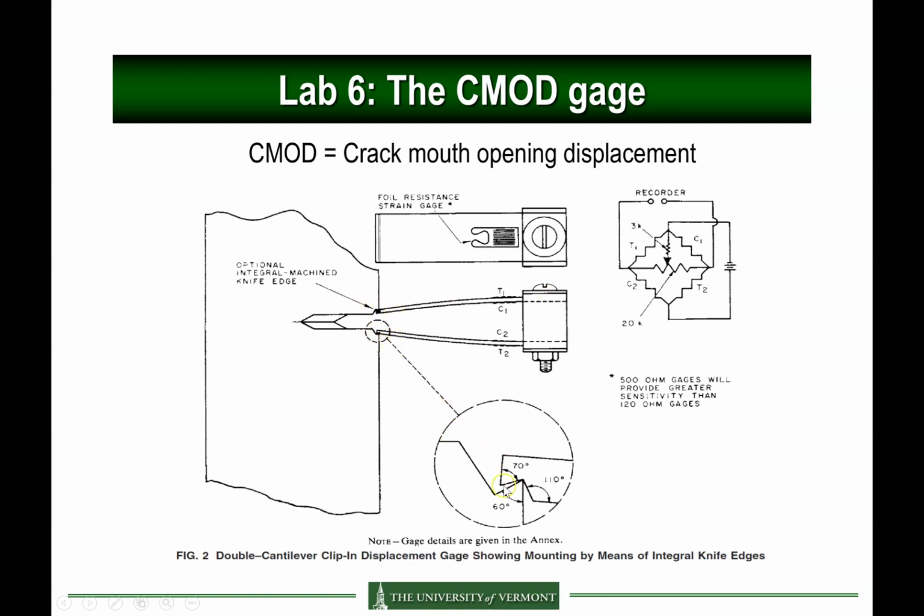Okay, so our specimen has this notch design, so we can attach directly at the mouth of the crack. So for us, the crack here is right here. Remember that the crack is actually measured from the pin center. So we are not directly under the center of the pin, but that's good. It's not going to affect the measurement at all.